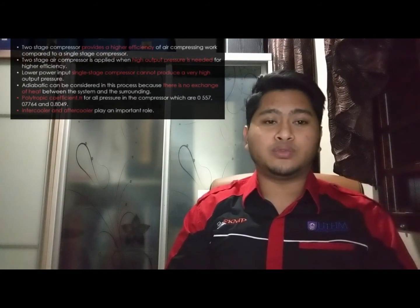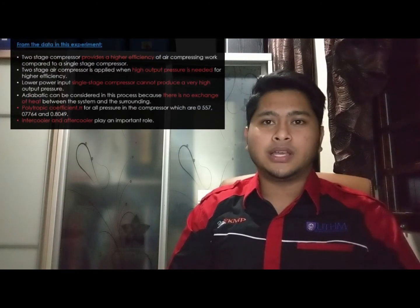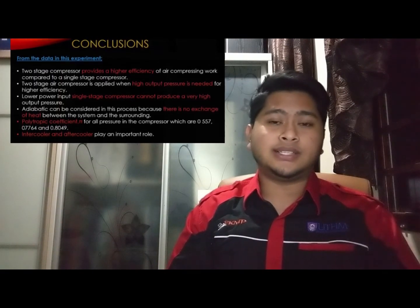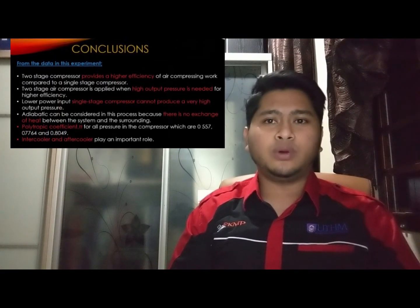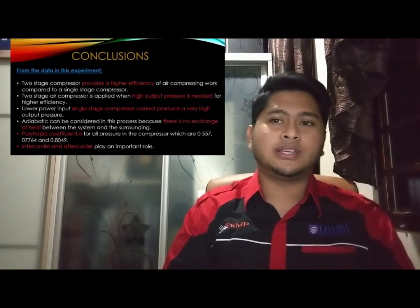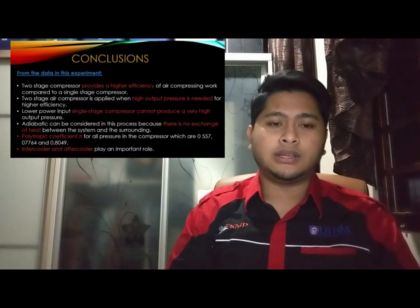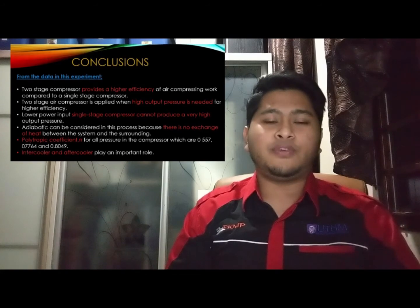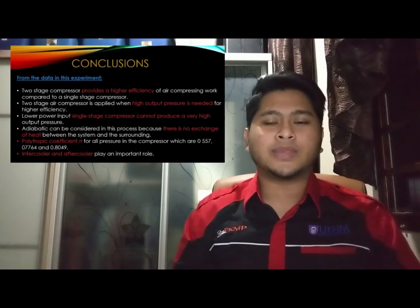I'm going to present the conclusion and recommendation for our experiment. As for the conclusion, from the data in this experiment, we can conclude that a two-stage compressor provides higher efficiency of air compressing work compared to a single-stage compressor. A two-stage air compressor is applied when high output pressure is needed, for higher efficiency and lower power input. A single-stage compressor cannot produce a very high output pressure because there are mechanical limitations for the single-stage compressor.